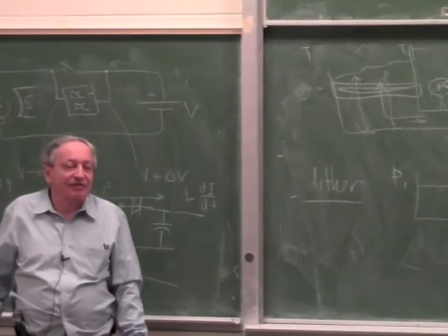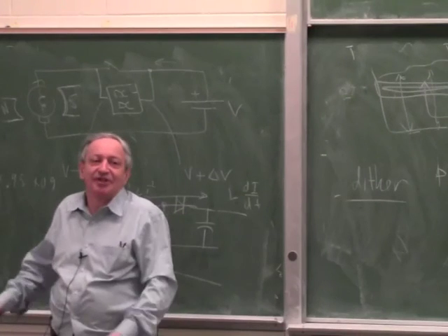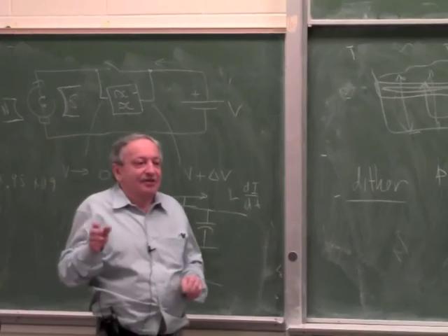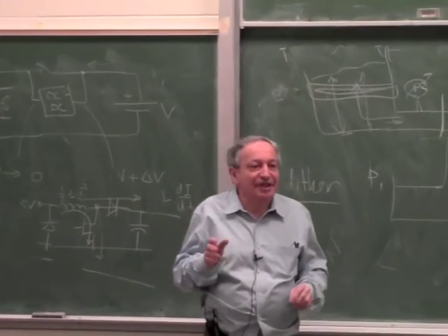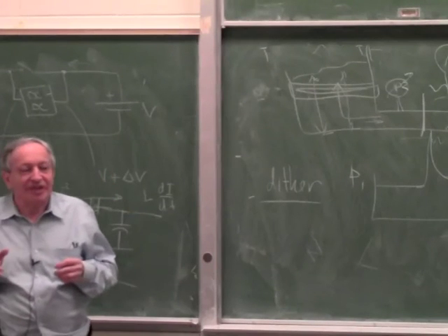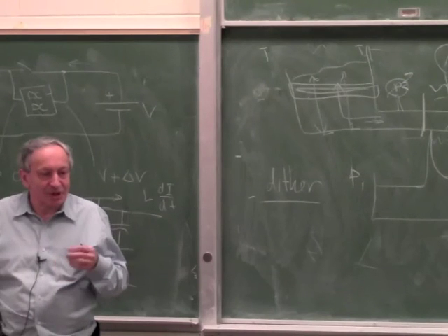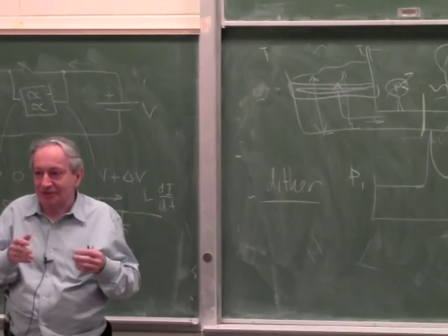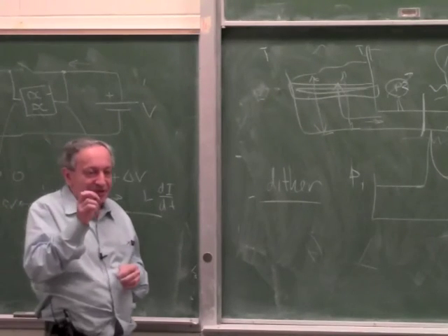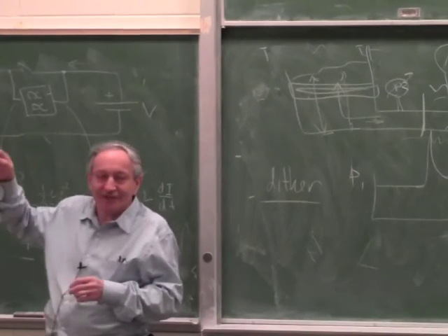If you need a very precise servo, like I say, it's used in gyroscopes or things where the smallest amount of friction can cause a problem. Like if you want to make what's called an inertial navigator, which is based on a gyroscope, you have to integrate the acceleration twice to get to position. But if you have a very small static error, and you do a double integration, this error will grow to infinity.